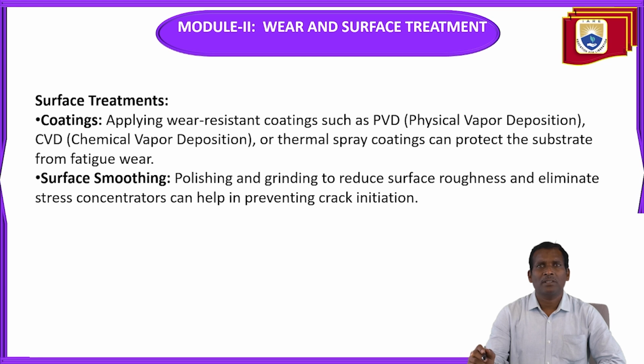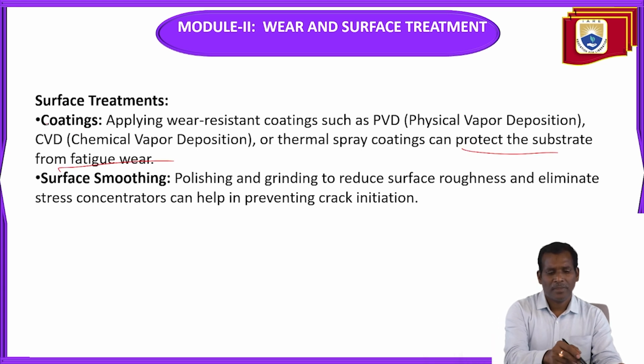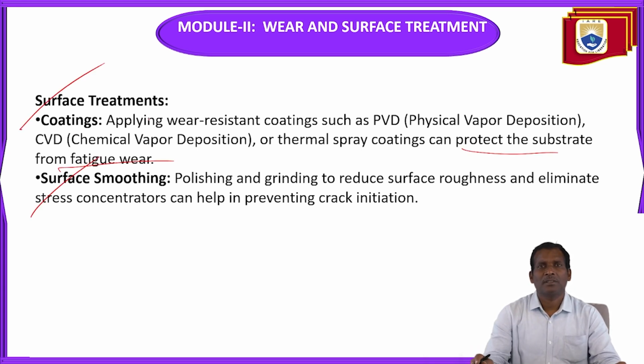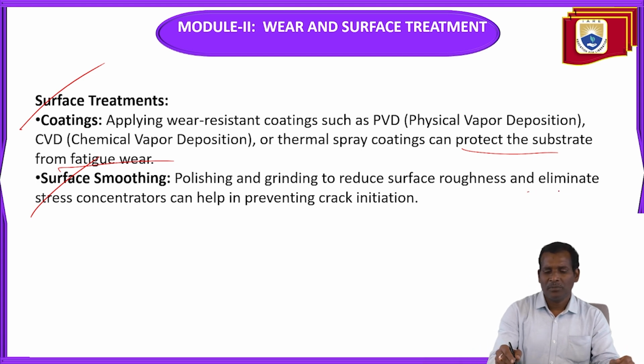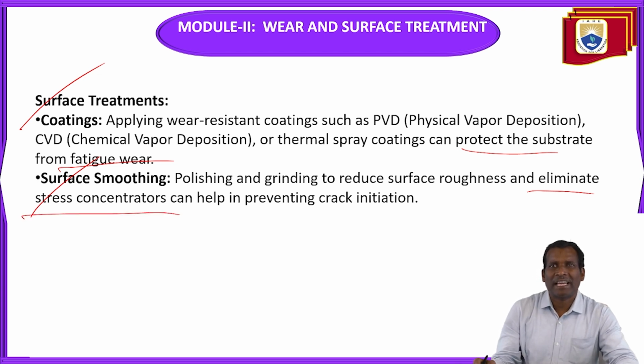Coating means applying wear resistant coatings such as PVD, physical vapor deposition, CVD, chemical vapor deposition, or thermal spray coatings, which can protect the substrate from fatigue. And then surface smoothing: polishing and grinding to reduce surface roughness and eliminate stress concentrators can help in preventing crack initiation.